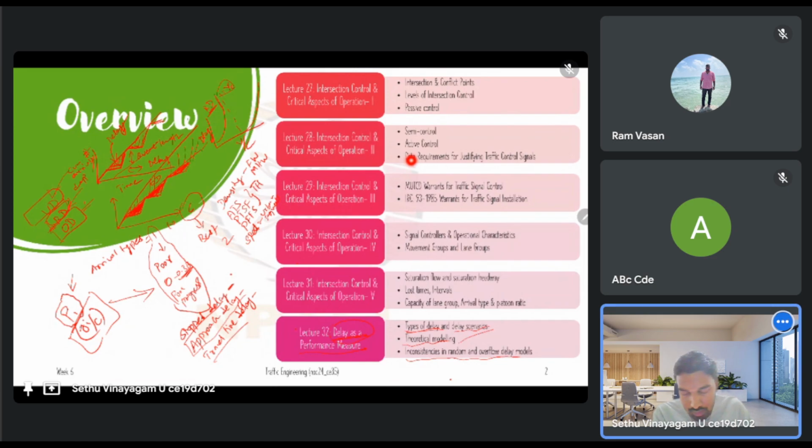And if you look at the right side, this is from the overflow delay model. That says at V by C equal to 1, the overflow delay is 0, right? Though V by C ratio equal to 1 is not an oversaturated condition, it does not mean the overflow delay is always 0. Because of the random failures of the cycles, in some cases we will have some excess delays over the uniform delay. So saying that the overflow delay will always be 0 is also not realistic.